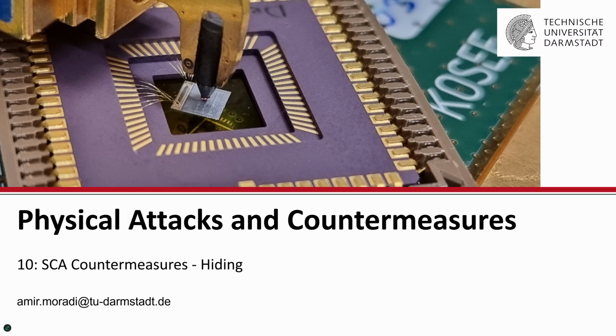We learned a lot about different side-channel analysis attacks, particularly power analysis, which is similar to EM analysis. Instead of measuring the power, you can measure the electromagnetic radiation of the chip and perform the same attacks that you have learned. Now we move toward countermeasures and the schemes known up to now to counteract these kinds of attacks, how to protect the implementations against them.